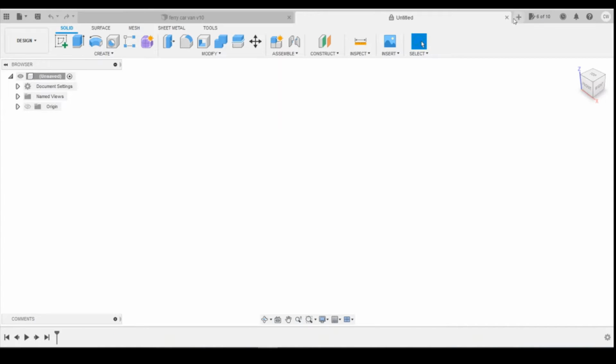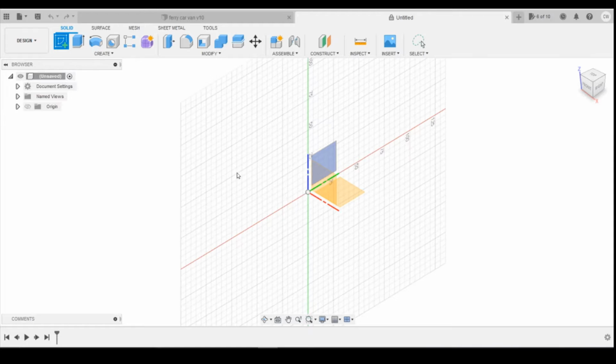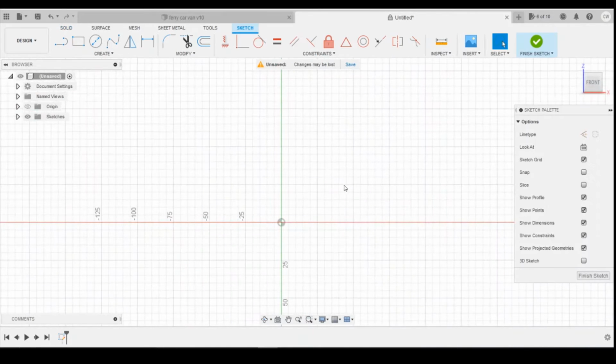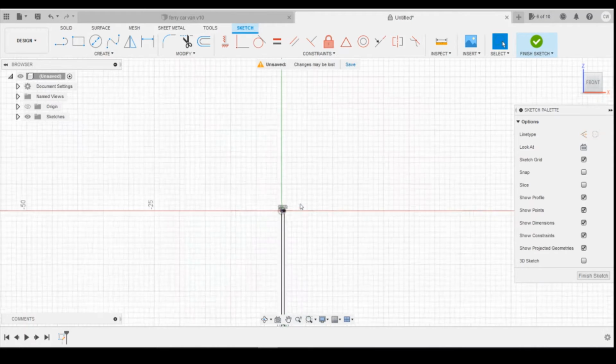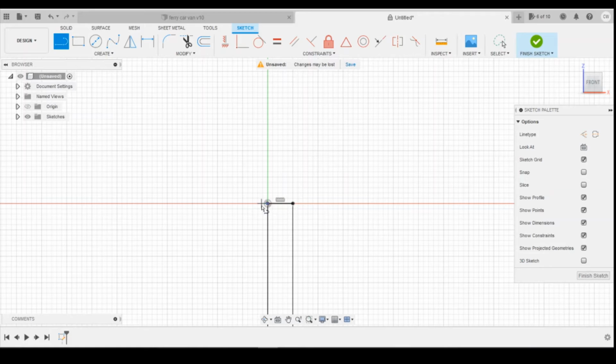I'm going to create a new sketch here, create a sketch on side plane, and I'm going to work rough dimensions out. So I'm going to use the origin point line coming out as 0.5 millimeters, zoom right in on that, and then we'll create another one going in the other direction, again 0.5 millimeters. I'm going to create two vertical lines, going to go 0.2 millimeters high on each end of that main line I've just drawn there. Just drag these to the outsides.